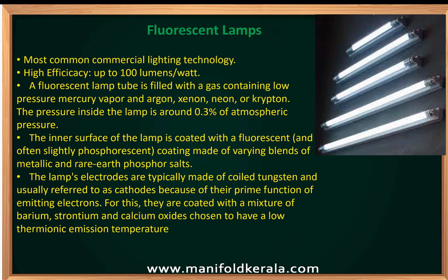Next, fluorescent lamps. The most common commercial lighting technology nowadays, though fluorescent lamps are being replaced by LED lamps. High efficiency or efficacy, which is 100 lumen per watt. A fluorescent lamp tube is filled with a gas containing low pressure mercury vapor and argon, xenon, neon or krypton.